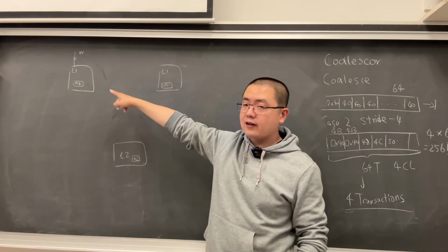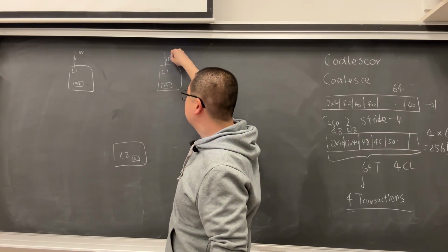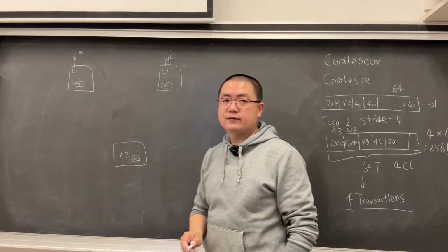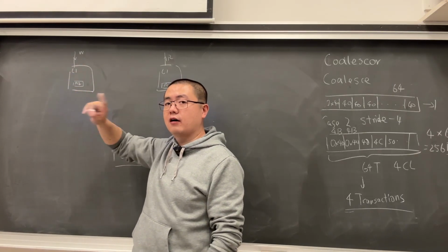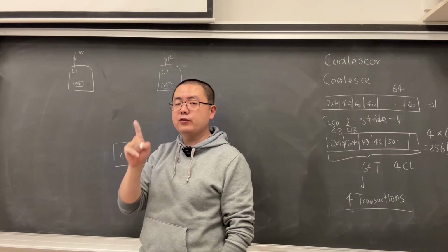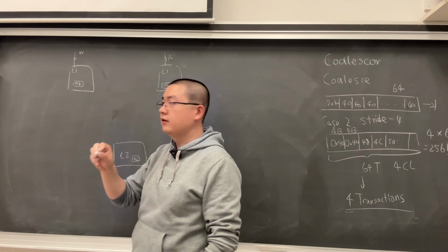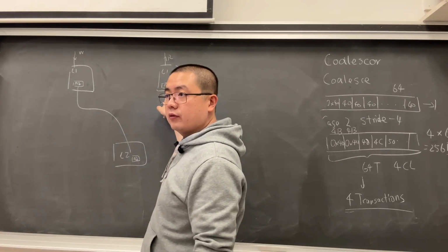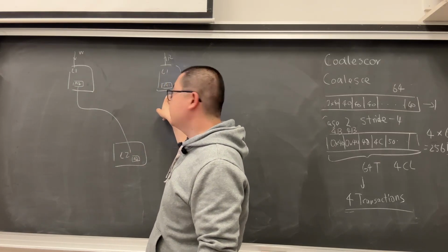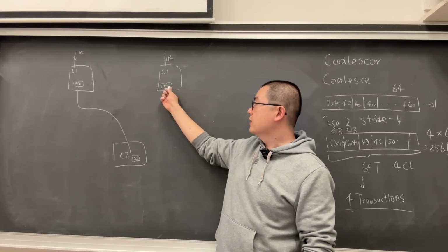What if after that one is doing A2, we do a read? We're reading A1 here. By the way, remember GPU L1 caches are all write-through caches. We don't say it's write-through or write-around, but it's a write-through family. Okay? So A2 will also go to L2, but this one, if we don't have careful consideration, will still have A1.